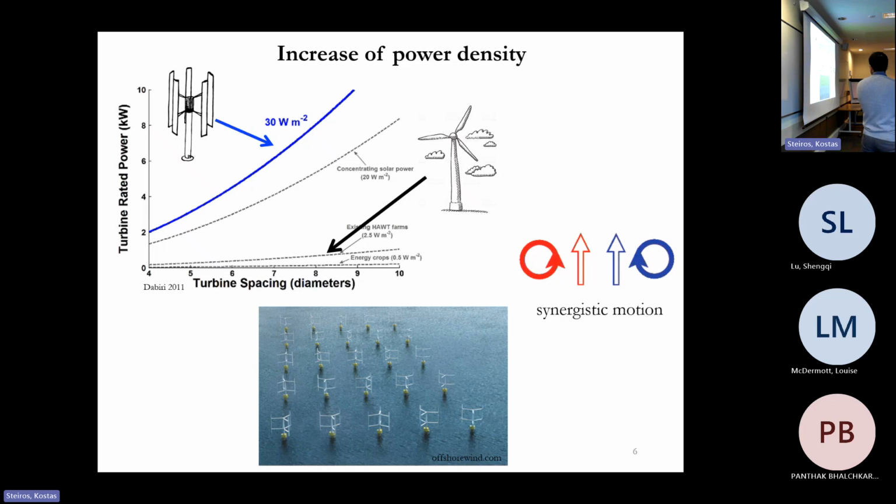However, what has recently been done is that we now start clustering wind turbines together in a wind farm, right? And as we discussed before, when we saw the aerial photograph from Horns Rev, what happens is that the wake of one wind turbine falls on top of the subsequent one, and basically they sabotage each other, so they lower each other's power production. Okay, so this is a negative effect.